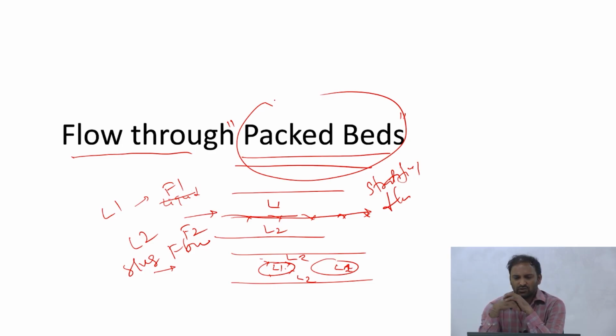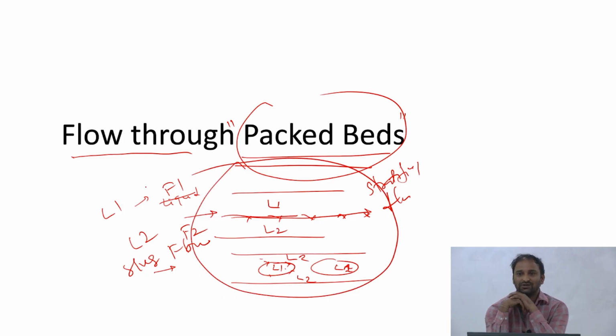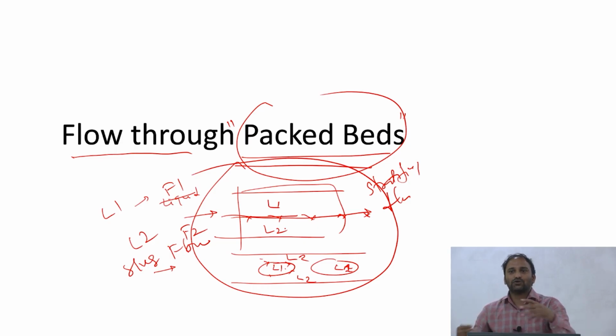Why do you say the less porosity, the more the break? Are you talking about porosity in this case? Because if I look at this, your entire column is filled with the liquid, so there are no pores as such. You have a liquid flowing through a column. You should imagine a liquid flowing through a bed of solids, where there are channels available for the liquid to flow through. If I have one or two different fluids, it gives more chance for the liquids to interact.